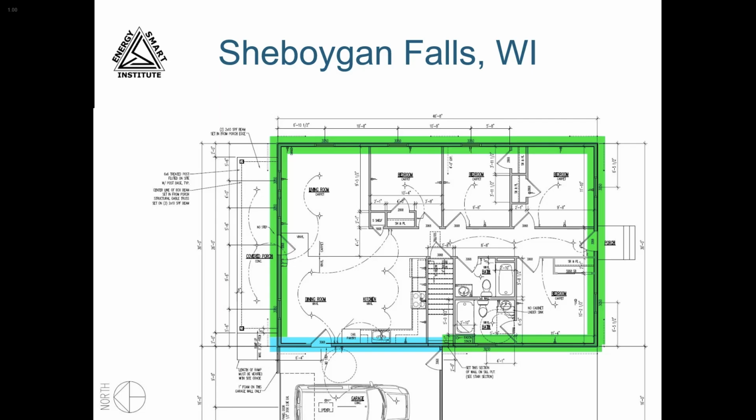Had the basement been unconditioned and built according to this plan, with a door at the top of the stairs and open at the bottom, this stairway would also be unconditioned, in which case our envelope walls would be the stairway walls, and they would be modeled as walls to unconditioned space. They're also cold walls, but we used blue for the garage, so I would highlight these purple. For now, we don't need to worry about any of those things because the basement is conditioned.